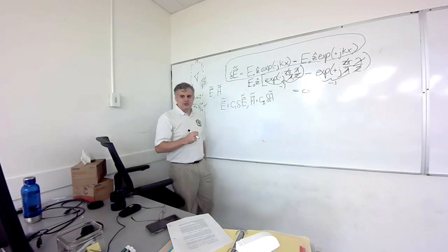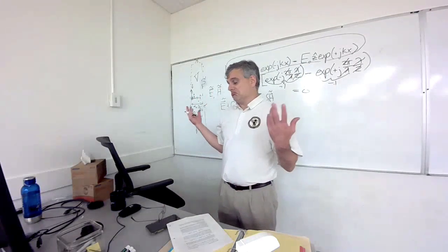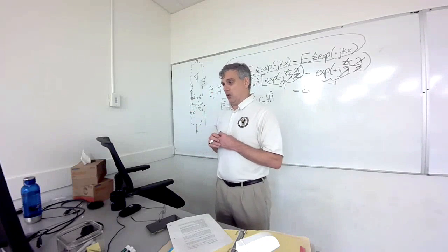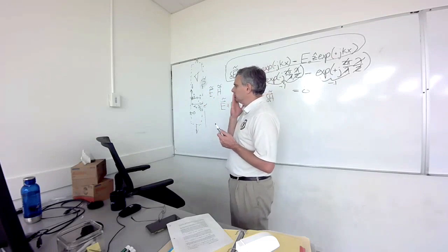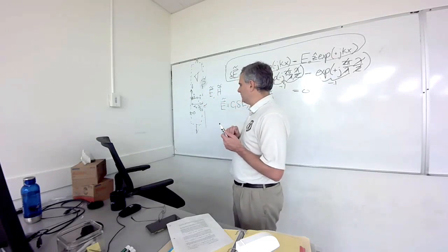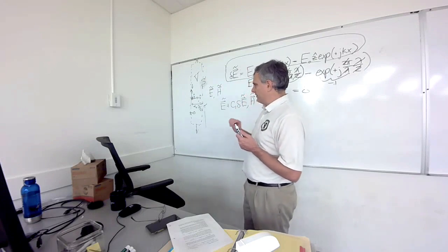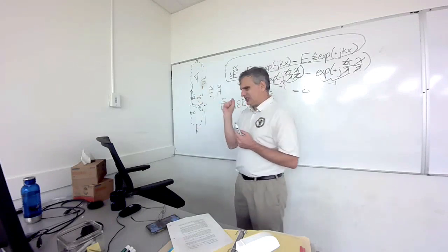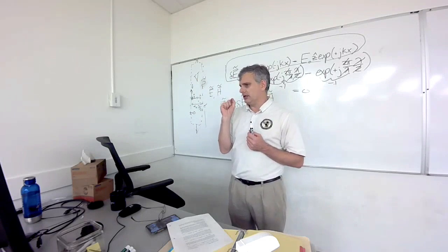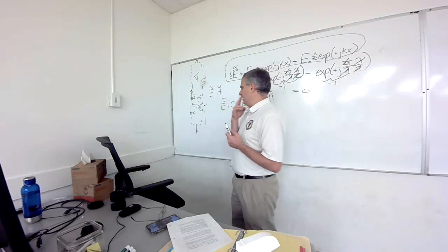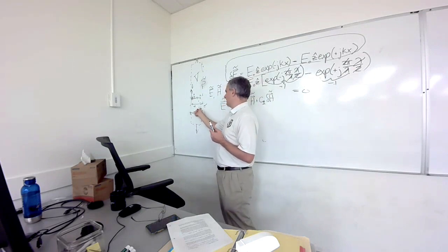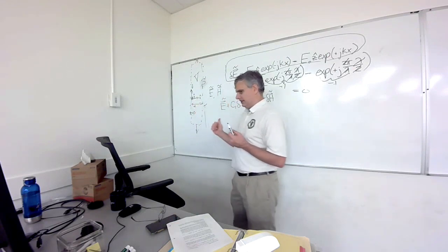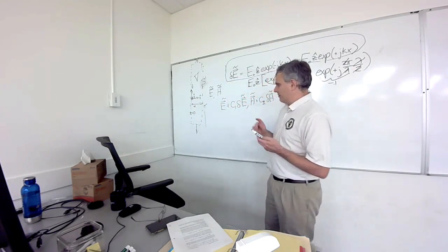So you can see that in a lot of these problems, for all intents and practical purposes, uniqueness exists. We just can't add some of these resonant modes. You say, well, wait a second. Hold on a second, Professor Dargan. What if this was uniformly lossy and it just had a little bit of loss, and let's say that D was wider than a wavelength, wider than lambda over 2. Couldn't I still treat this like a parallel plate waveguide?